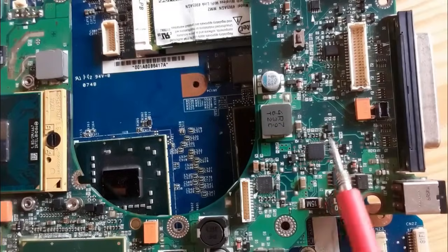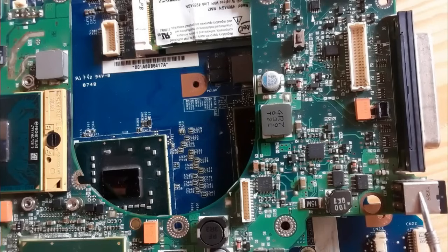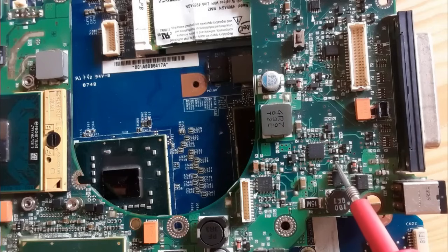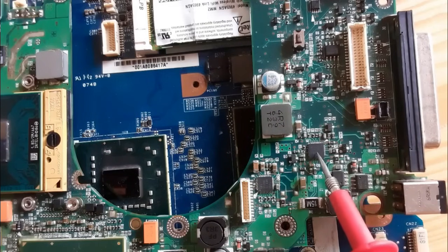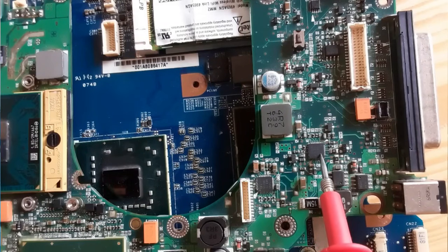Now we're going to see the charge IC. You will always find it near the power jack and near the power component. As you can see, this is the power component, or the protection component. This is the current sense resistor, and this is the charge IC. If there is a problem in the charge IC, the laptop cannot be operated. The charge IC is the control management IC for the power circuit.